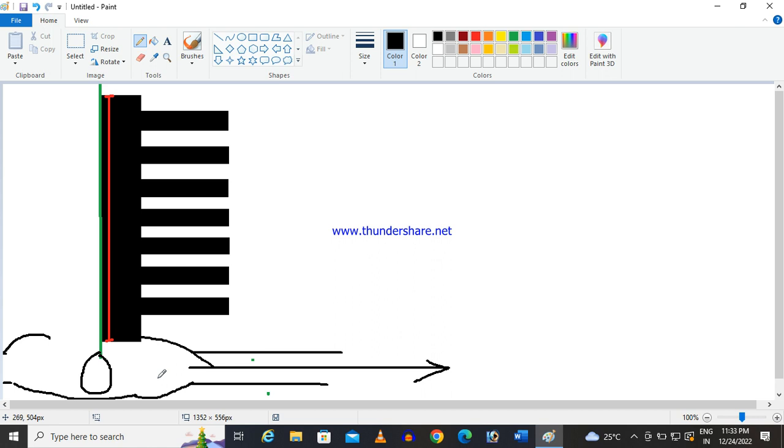Your x-axis is relative travel of the disc or relative opening, and your y-axis will be flow coefficient. Based on that, your valve sizing is characterized, that we all know. That part we are not going to discuss today. Today we are mainly concentrating on this fin tube assembly.